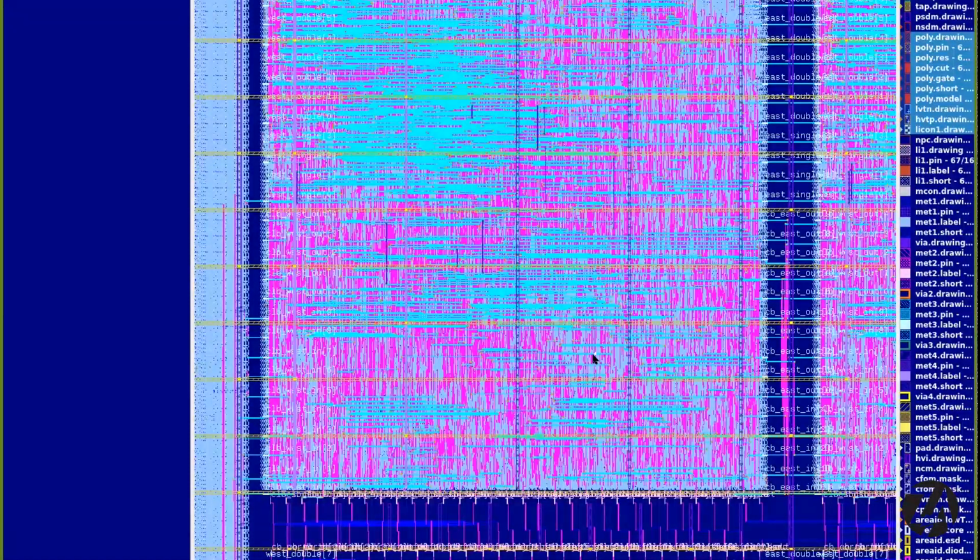Yeah. And then, I suppose I was expecting to see something much more regular because, well, this is an interesting thing. FPGA fabric is so regular. This is actually my personal research direction. I think that synthesizing FPGAs like this is good because it's easy and it makes it accessible. But I think it leaves a lot of performance on the table because at the end of the day, you're just trying to put these standard cells and arrange them as best as you can, and you're not going to use all the available space. You're going to have too many extra.